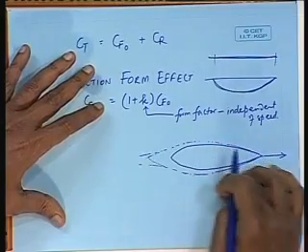So, the pressure distribution changes from what it would be if there was no viscosity, and since the slope reduces, the contribution of the aft body, the aft pressure forces, for reducing the resistance reduces. So, effectively you have an augment on the pressure resistance because of the existence of the boundary layer.